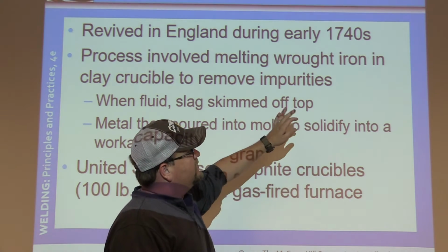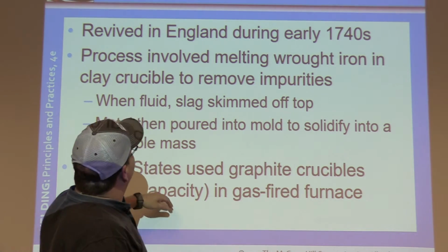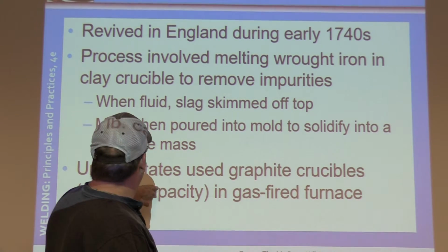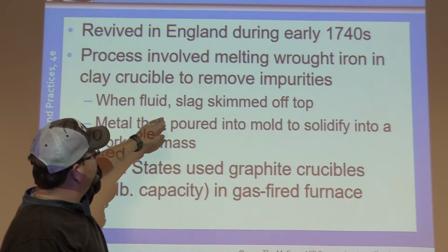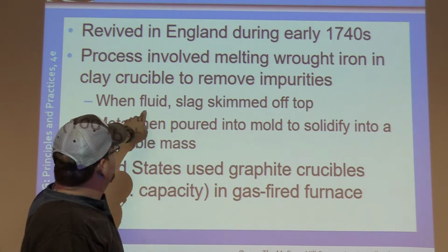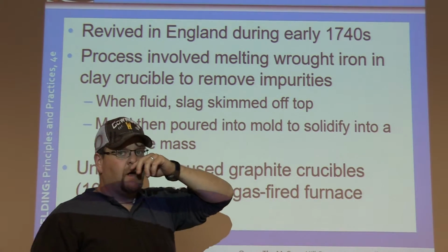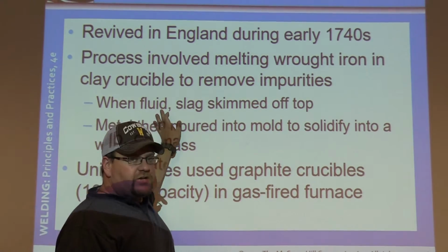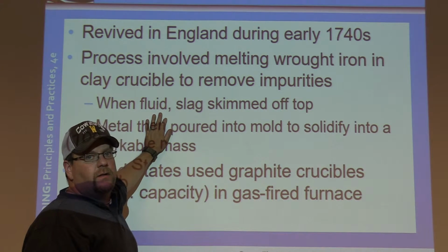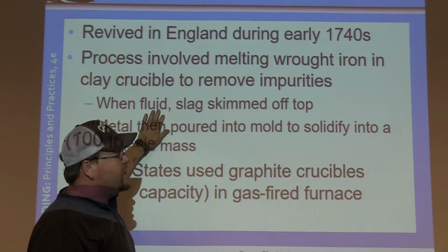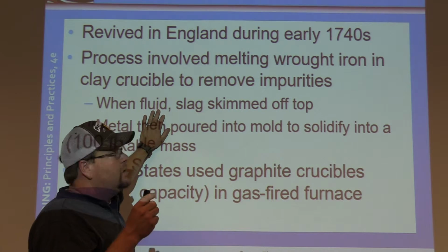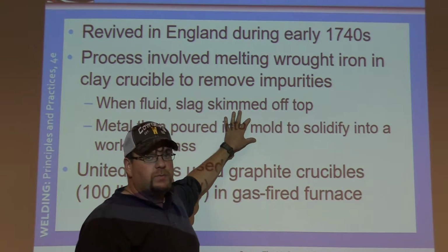So for example, in the 1740s, they found out that by melting the steel, you can remove the impurities within. When fluid, the slag was skimmed off the top. This is the exact same thing that all electric arc welding processes still do today, correct? We make sure that that liquid puddle is fluid so it fuses together, it combines, and then the slag is pulled off of the top.